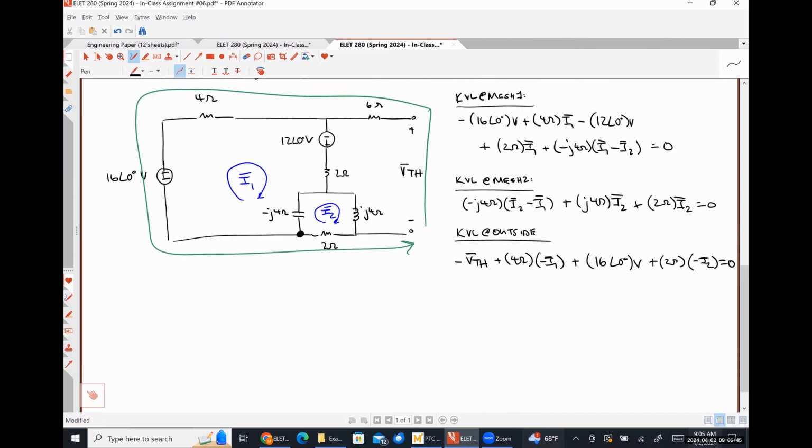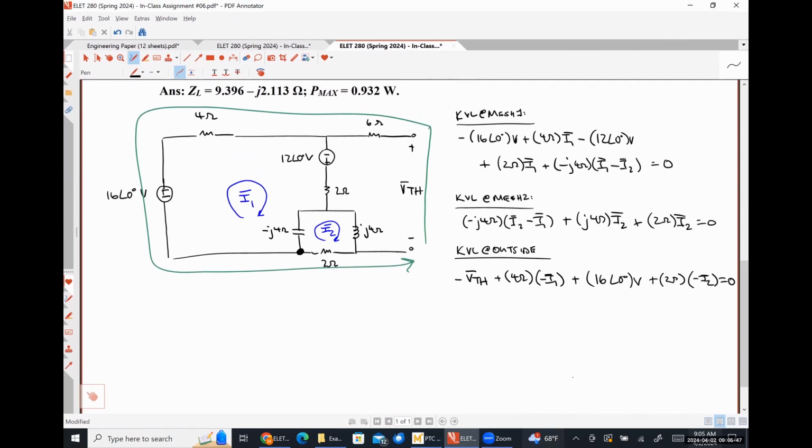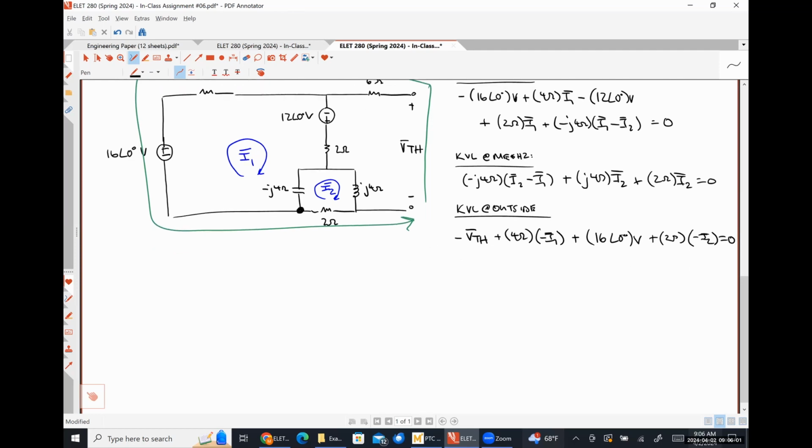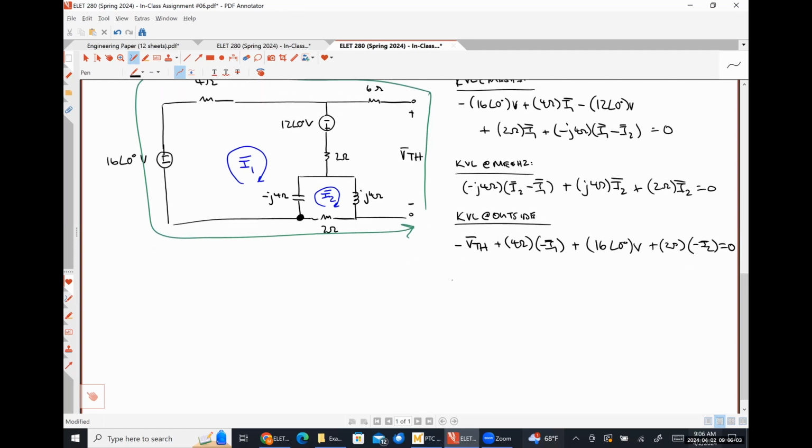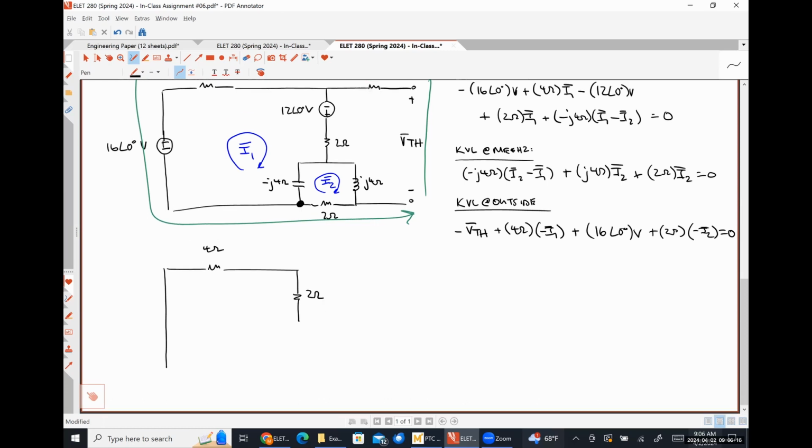Now, let's take a look at how we're going to find the resistance. So I'm going to start with something that I know is not going to work. And what I know is not going to work is a direct analysis of this thing. So if we looked at a dead network, my voltage source would be off. Here's my 4 ohm resistor. This voltage source would be off, so I have my 2 ohm resistor.